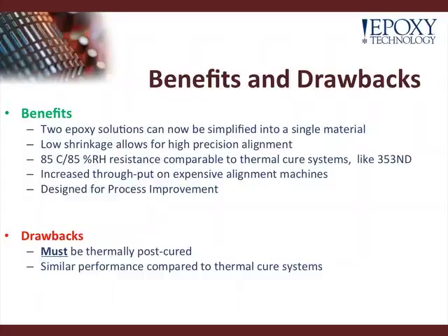With the UV hybrids, they were able to go in and quickly illuminate, align their parts. They could then take them off their machine after 20 seconds, rack them up, and at the end of the day, put all of those parts into an oven and cure them together. They were able to get, I believe it was near 30 times the throughput that they previously had.